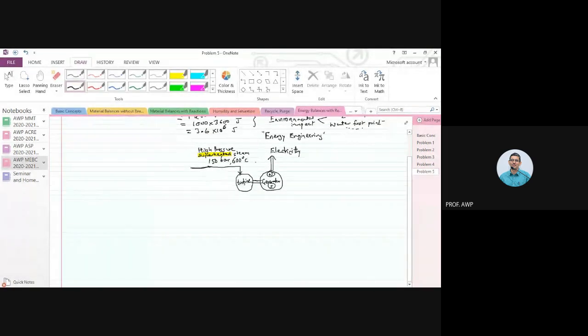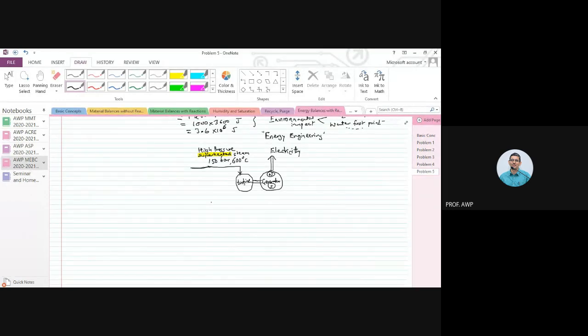We will only say that this superheated steam is supplied to this turbine that causes the turbine to rotate, just like you have a hydroelectric power plant, right? There is water that is flowing from a height that rotates the turbine, that rotates the armature inside the generator, and that's how it generates power. So instead of the water, it is a high pressure superheated steam.